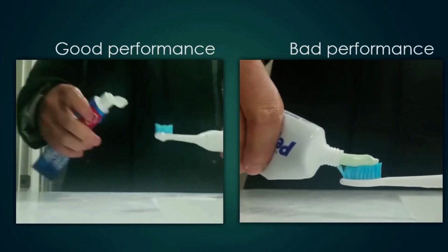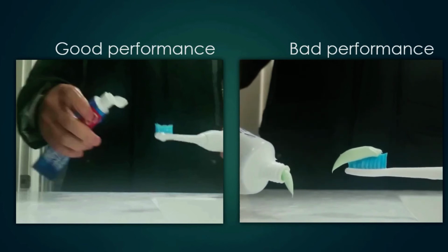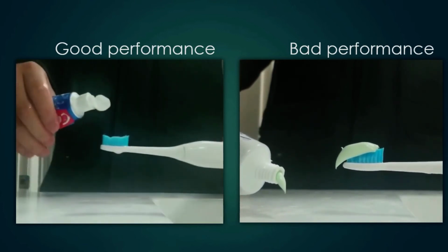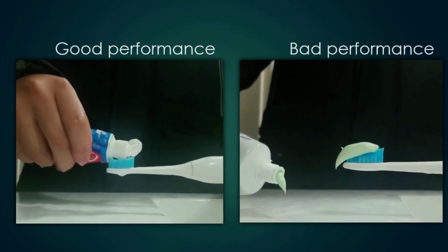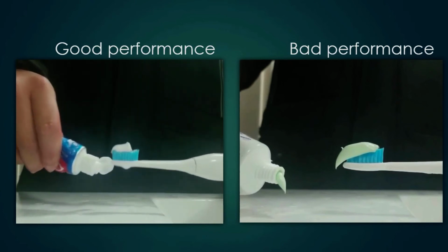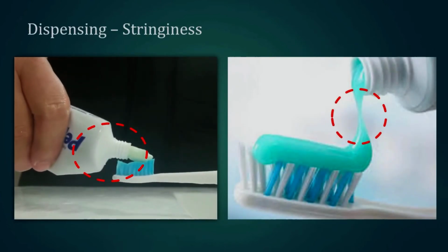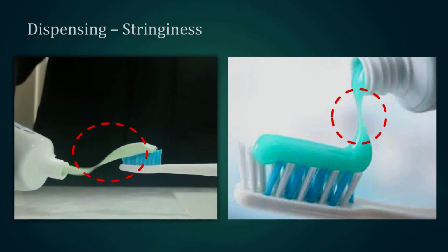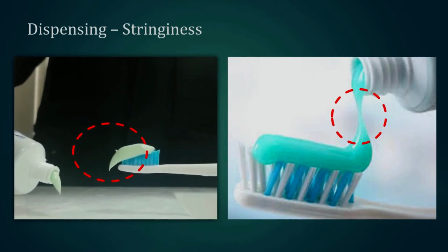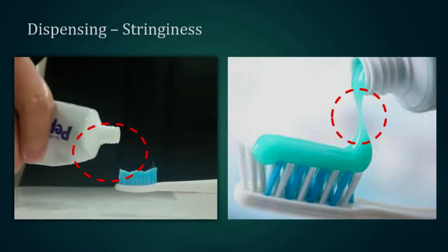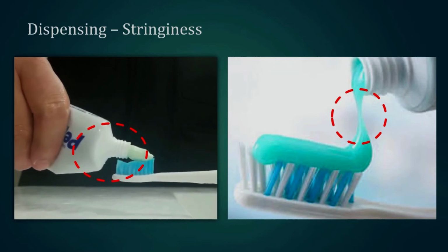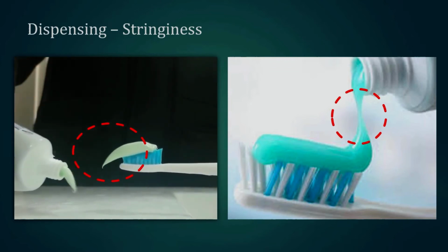If yield stress is too low, then too much paste will flow from the tube when dispensed. If yield stress is too high, then the toothpaste will be difficult to squeeze out. This means that a mid-range yield stress is desired. Clean breaking of toothpaste ribbons or extrusion is a property influenced by viscosity and thixotropy. A toothpaste's viscosity is primarily influenced by the choice and amount of thickening and binding agent used.